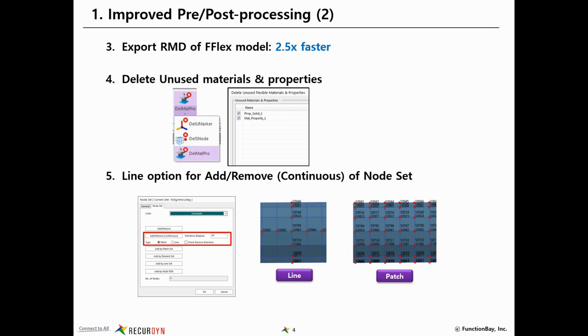And it's a similar feature with these delete the unused materials and properties. If you had been adding quite a few new materials, new properties, as you've been making edits to your model, you can come up with quite a list. And so that's a quick feature that you can just click once and it deletes anything that's not being used currently. That's a way of simplifying your model visually to make it easier to understand as you're going through your model.